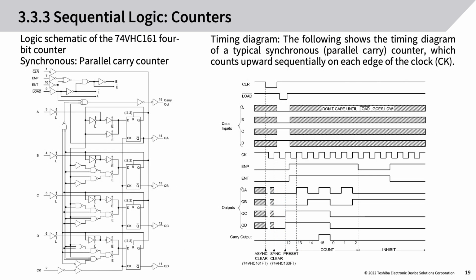Logic schematic of the 74VHC161 4-bit counter. Synchronous, parallel carry counter. Timing diagram. The following shows the timing diagram of a typical synchronous, parallel carry counter, which counts upward sequentially on each edge of the clock, CK.